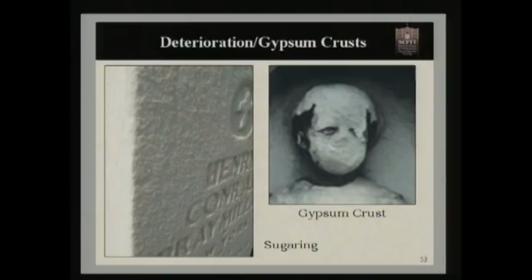is things like salt-laden cleaners like bleach. And what they do is they go in, get absorbed into the marble. As the liquid evaporates, the salts are left behind, they recrystallize, which grow inside the pore structure of the stone, pushing apart the internal structure. And what you have is small flakes of the stone, the crystals actually falling off. And we call it sugaring because you can run your hand down it and you get sugar. And it feels like sugar, it looks like sugar.